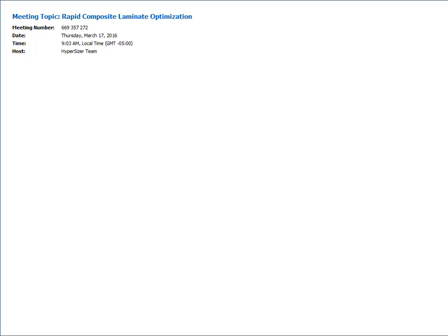We know from a manufacturing perspective it's quite challenging to make a part that has a variation in core height, and so it's easier to change core density than core height. So third would be core density, and fourth, the least priority, would be the laminates themselves, because it's considered a little bit easier to remove and add plies to meet your required stiffness and strength.